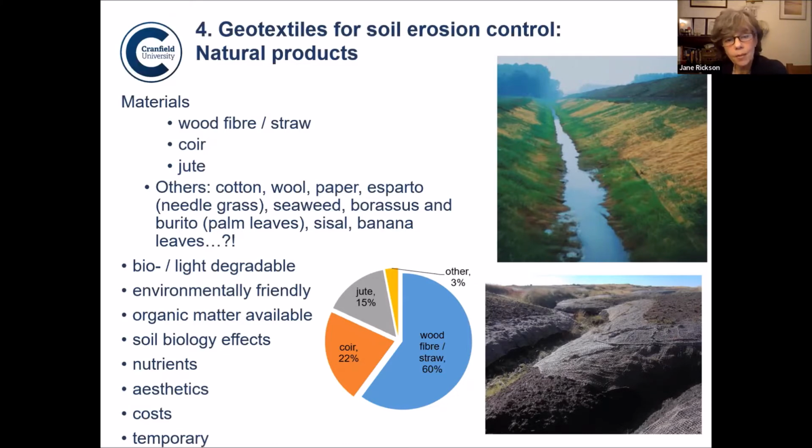They asked me whether banana leaves had any potential as a natural fibre erosion control mat. I did my homework, and I looked up the properties of banana leaves, and they really would not make a very good erosion control product. They don't have very high absorption, and it would be very difficult to use, and they don't have very good drapeability, which I'll talk about in a minute.